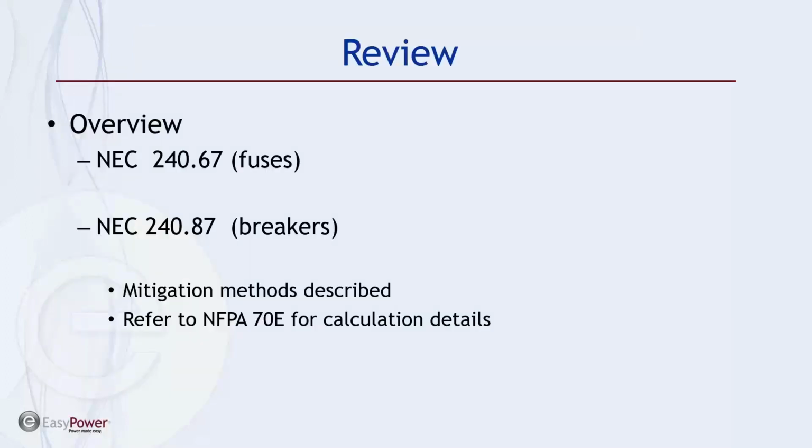Okay, so I apologize for some of the wishy-washy discussion, but there is a fair amount of room for engineering judgment, and that's, I think, what's being guided here. There's no direction on the incident energy that you need to achieve, just the fact that the equipment needs to be included based upon this criteria of 70 milliseconds being the long trip time.